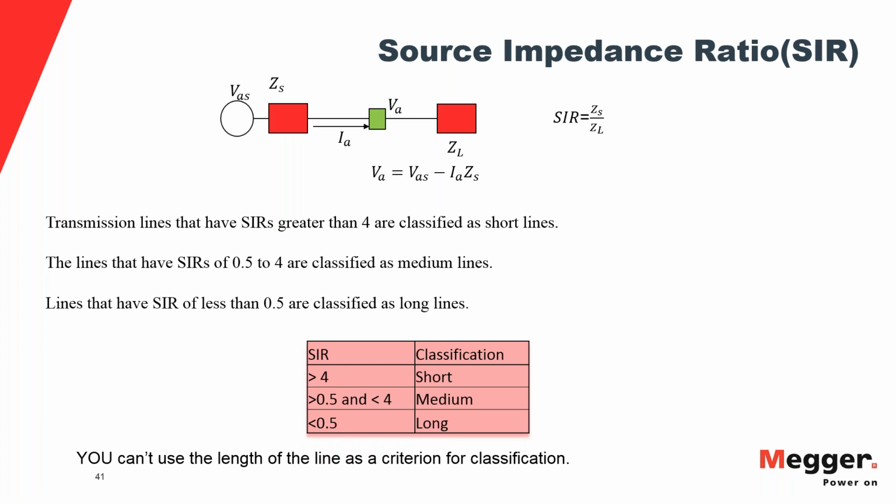In other cases, the manufacturers are more open and let you define what to use as the medium, and then they define the signal communication interface. But you have to use some sort of communication path or channel between one end of the line or one relay and the other. Could be a combination of fiber optics and a dedicated channel.